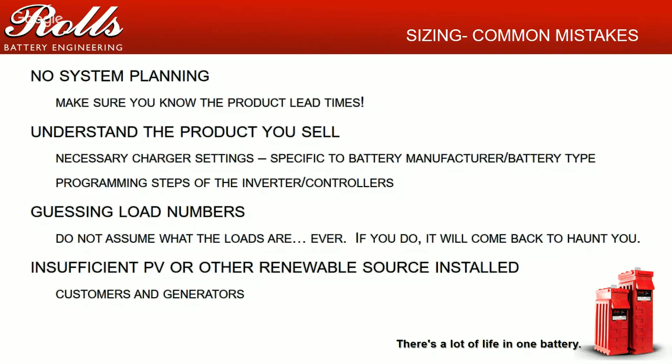Guessing load numbers. Don't ever assume what your loads are. When you're designing a system, you need to have a basic understanding of how that customer is going to use that system. Often installers, when they do a system quote for a customer based on a load analysis, will make the customer sign and understand that they've designed it for this specific load profile, and if that load profile increases, that battery-based system will be undersized, and that'll cause problems.